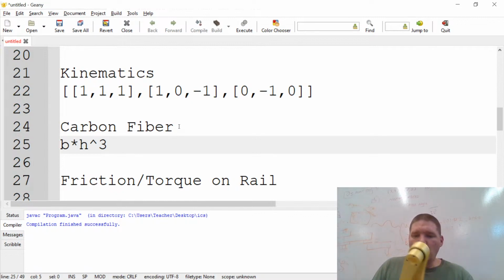I'm printing with PLA, and by the way, of PET, ABS, all that stuff, PLA is actually the one that has the highest Young's modulus, so it's actually going to do the best. That's why I'm printing with PLA, and it smells good, and I have a lot of it. If they're suggesting that I go to carbon fiber, I might increase the strength a little bit, but I could just do a humble approach and increase the dimension, and I can increase it a lot more than getting the carbon fiber, and I save a lot of money.